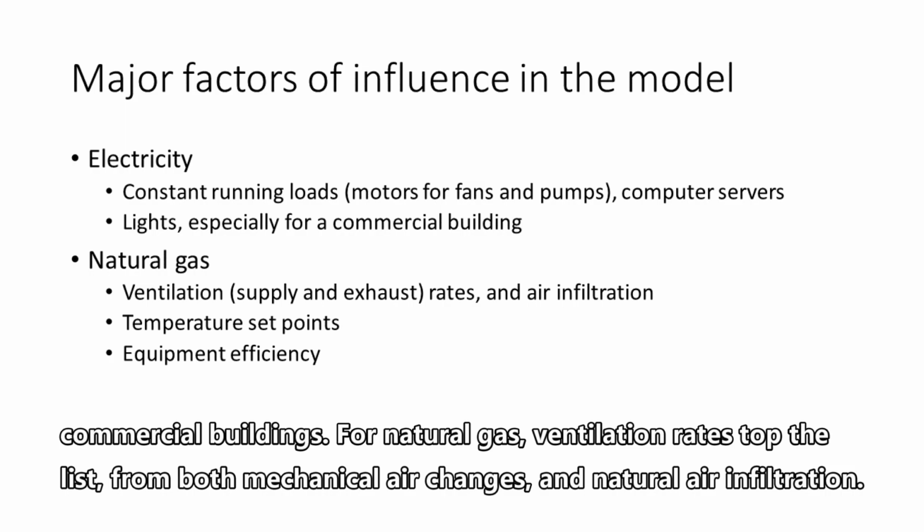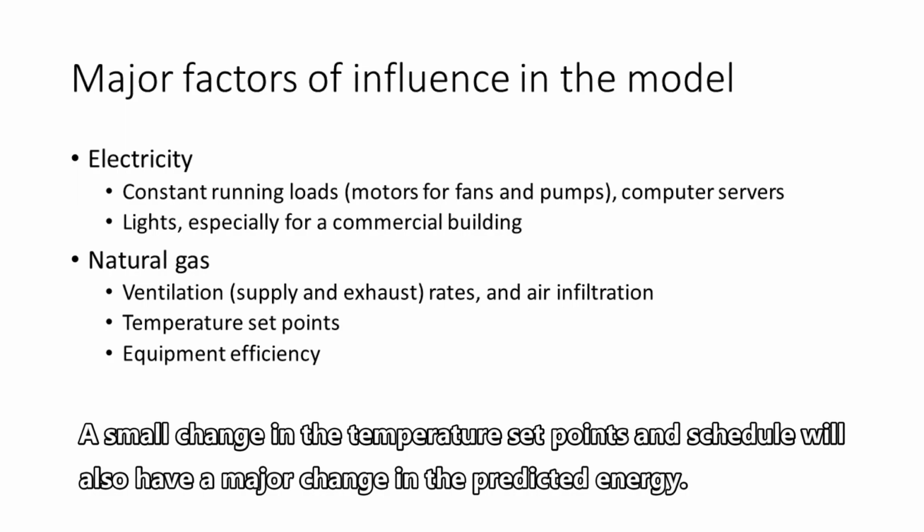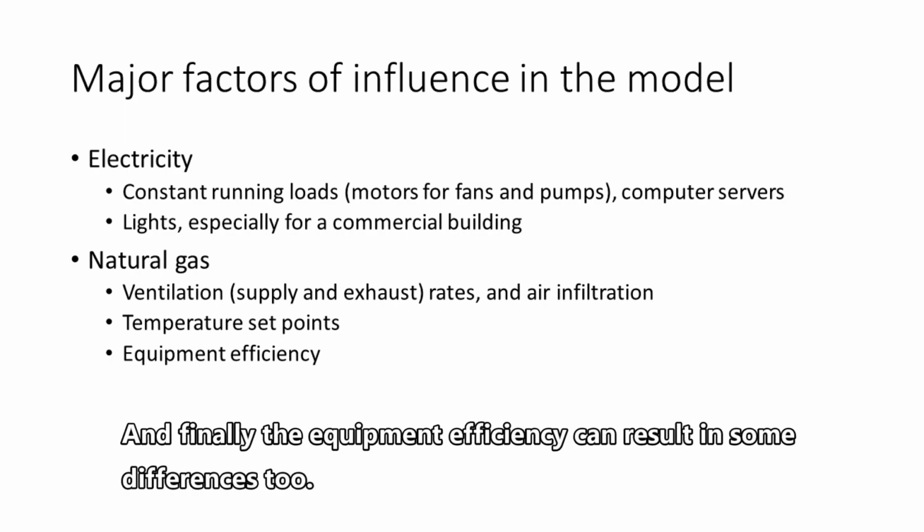For natural gas, ventilation rates top the list from both mechanical air changes and natural air infiltration. A small change in the temperature set points and schedule will also have a major change in the predicted energy. And finally, the equipment efficiency can result in some differences too.